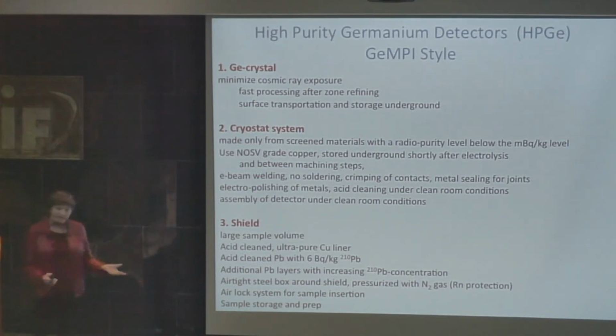How do you put the thing together? In the end, you have to do electropolishing of all the metals and acid cleaning, and you have to be in a clean room because you don't want radon plate out to occur while you're doing all this other great stuff to keep it clean.